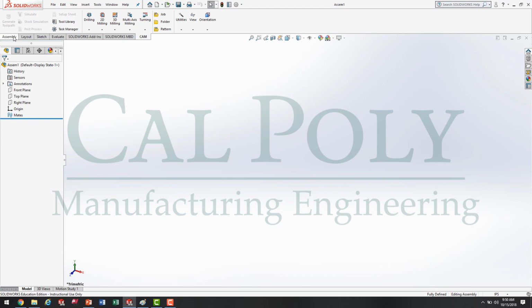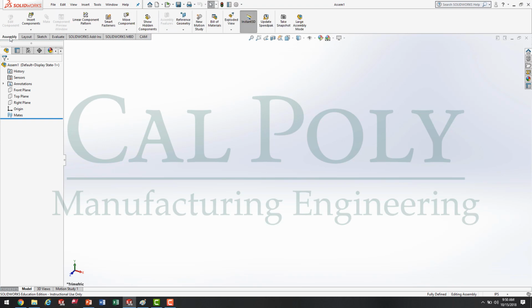First, I'm going to move over to the Assembly tab up on the ribbon bar and click on it. The Assembly tab is going to be the main tab we use in the assembly environment for this class. We're going to mainly use Insert Component to bring in existing part files into our assembly. We're going to use Move Component to move the component around and show you how the different relationships constrain the degrees of freedom of a part. Then we're going to do an Exploded View in order to virtually explode the parts to show how the assembly gets put together.